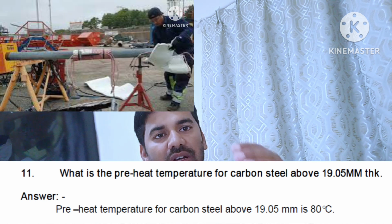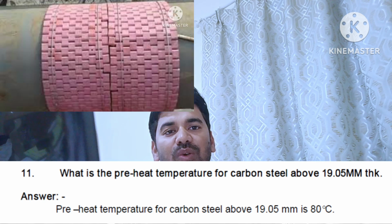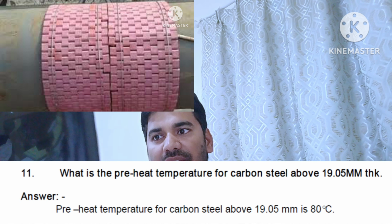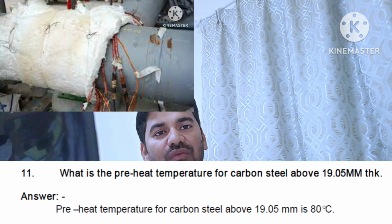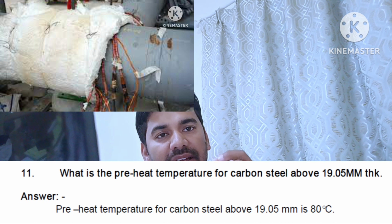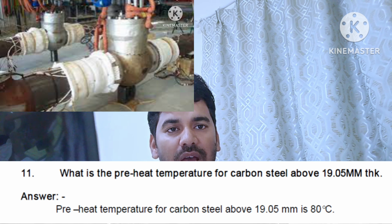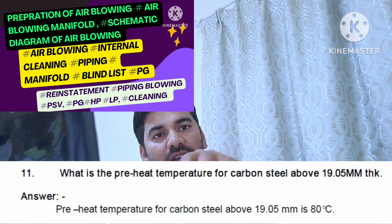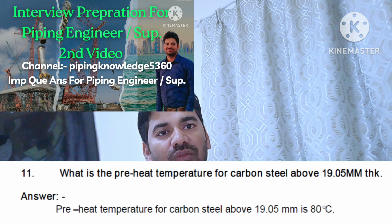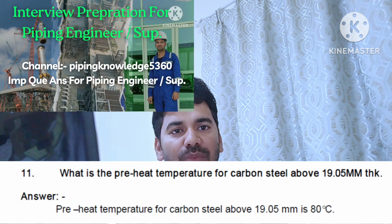But if the thickness is 19.5 mm or more, then you need to do preheating before you start welding, and the preheating temperature is 80 degrees Celsius. For normal pipe, if you are working in a cold place like Russia where the temperature is always minus, then for any pipe you want to weld, the minimum pipe temperature must be 10 degrees.